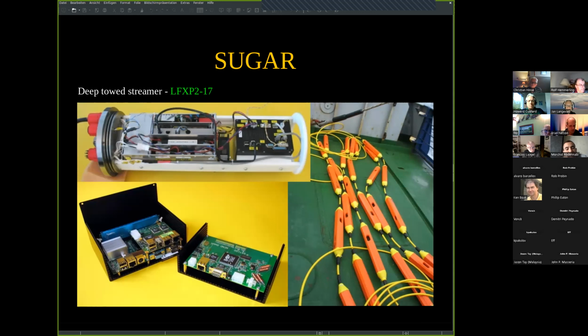And basically what it did, it converted the serial stream that came in into 24-bit entities for the hydrophones, and then the FPGA and microcore would send these signals to a bottom PC, which was quick enough for this purpose.